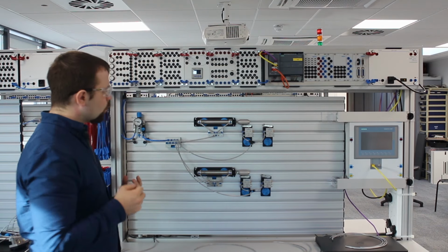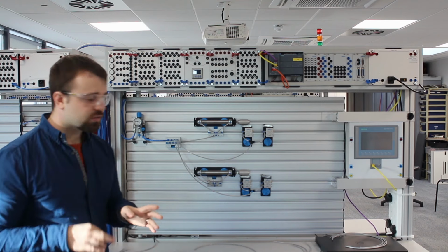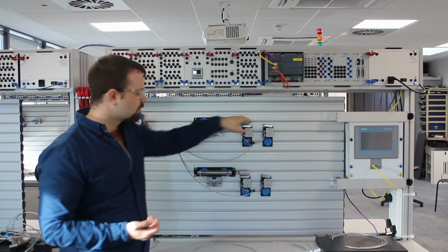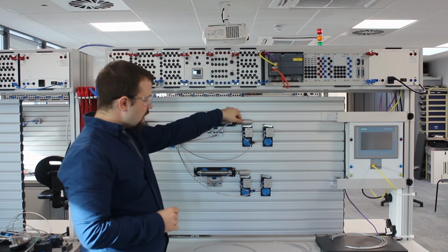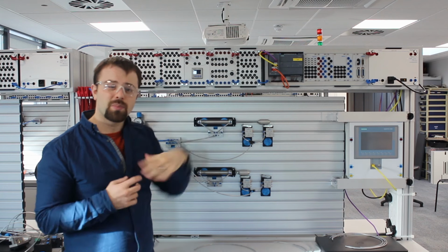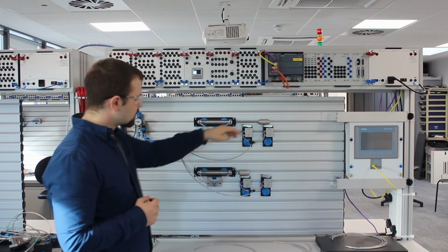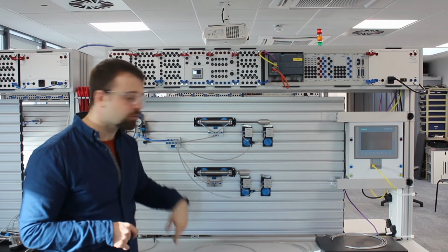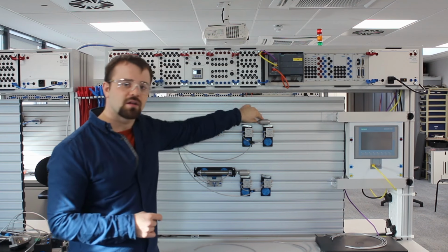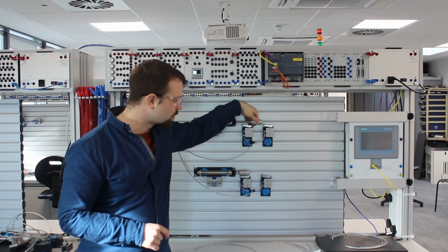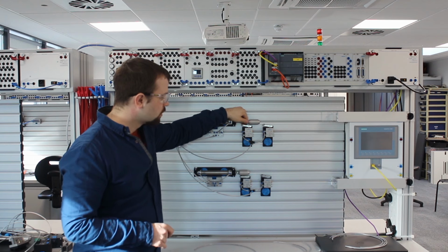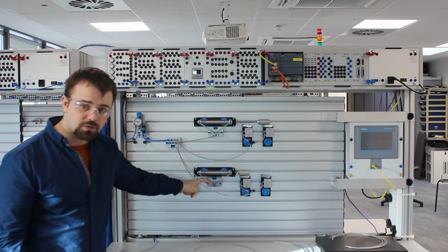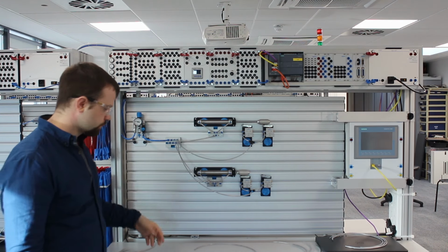And earlier I was saying you would think you would start with the A+. You would think the first thing to do would be to get that to work. But really I like to approach that last. So the second step, A has already gone plus, now B needs to go plus. So we can see that it is this roller switch up here that is going to need to trigger B to go forward, because A moves forward, now B has, and the last action we have is that this roller switch gets triggered. So let's wire this roller switch to 1/4 on this valve, which would cause this cylinder to go forward.